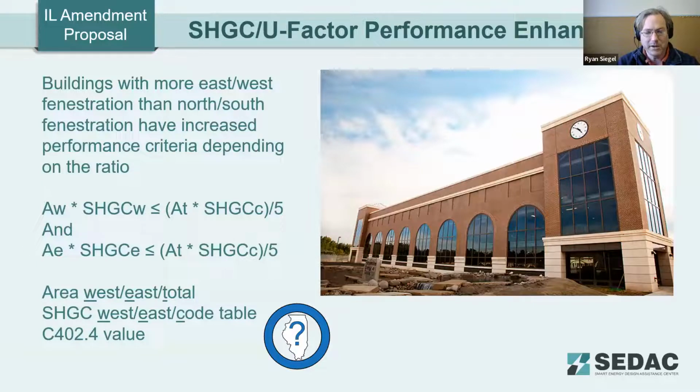So here at this building, we see this facility has a large expansive east-facing glass, and so needing to improve the solar heat gain coefficient performance, such that when you get that morning sunlight in, or conversely, if you had west-facing fenestration, that afternoon sun, trying to limit that increase in air conditioning loading just from that strong solar gain for east and west.